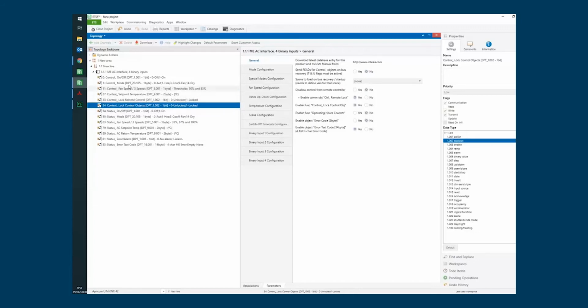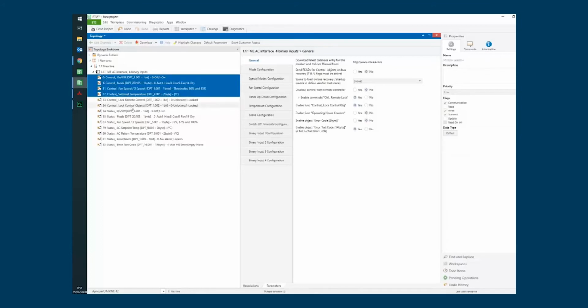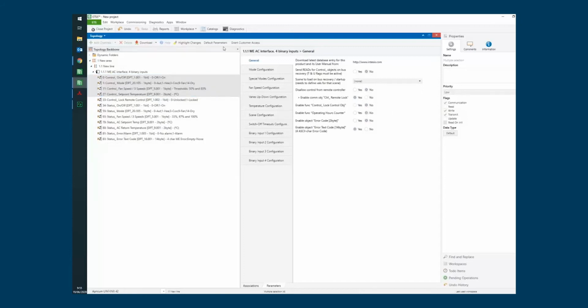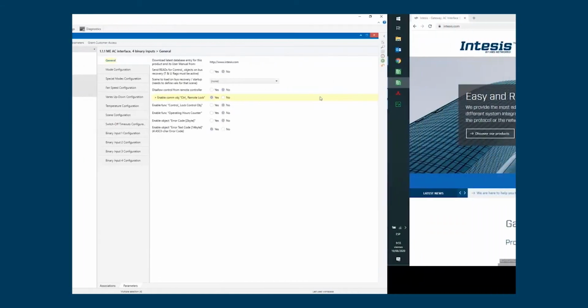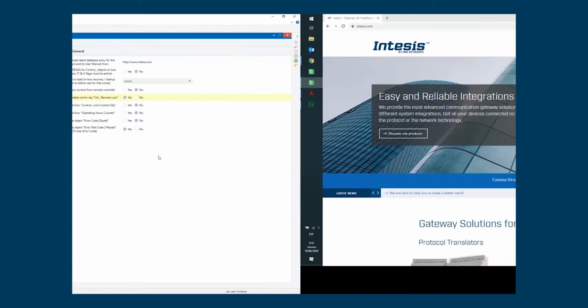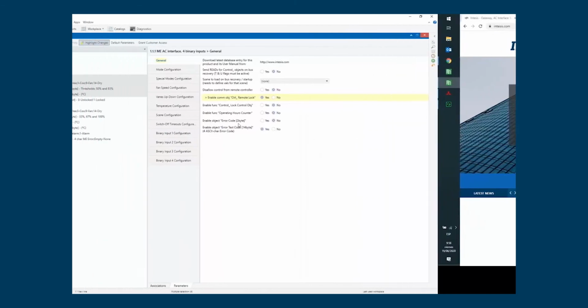If we send a 1 here, we will be locking the control of the AC unit from the KNX side. It's a kind of locking of the AC unit from KNX. I'm not interested in using it in my project because it will be a very simple control from the end user point of view. So I will not enable it.